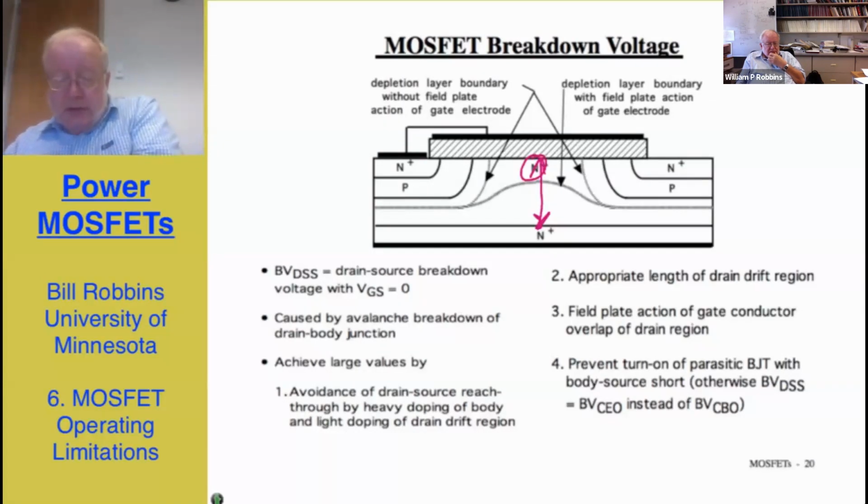is determined by what the breakdown voltage rating for the MOSFET is. And what we want to do is make sure that we use the device wisely and make sure that under all circumstances we don't exceed that breakdown voltage rating, and in particular if there are inductances in series with the MOSFET that may cause overvoltages, we may have to consider the use of appropriate snubber circuits.